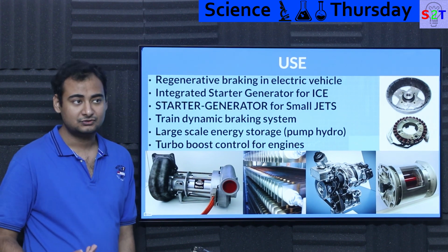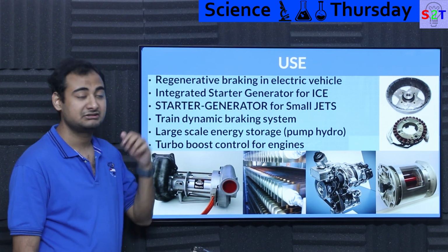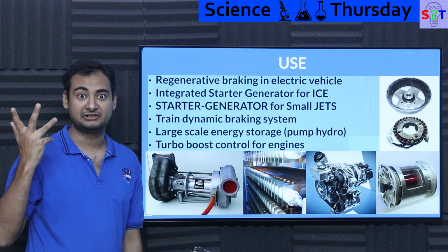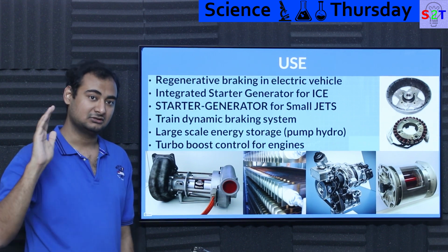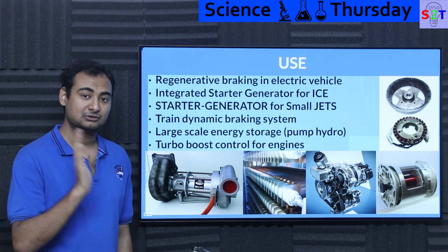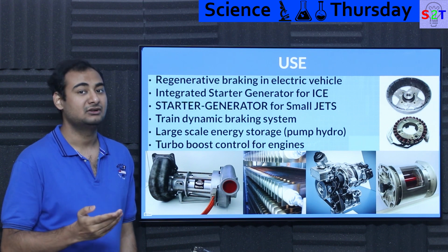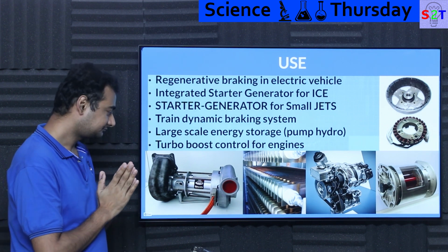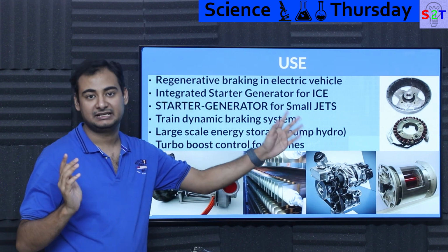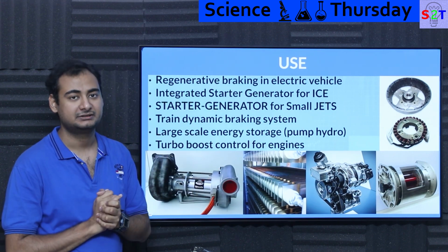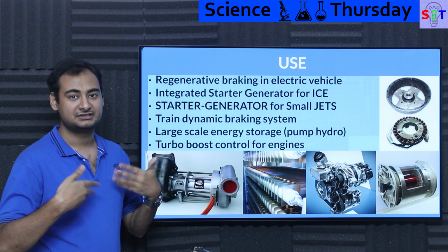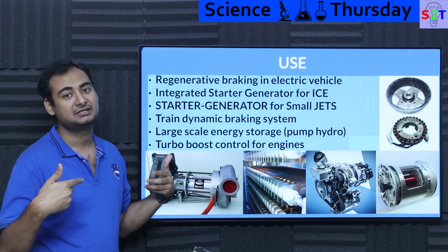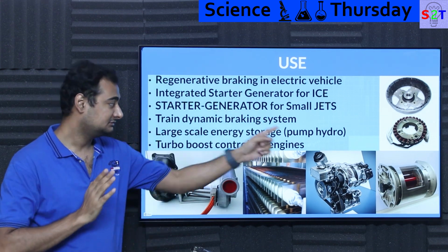Well, reality is, most of you have heard of it, specifically regenerative braking. Every time people are like, regenerative, what is that? It's like when you are going at, let's say, 100 kmph and you want to apply brakes. In an electric car, the brakes will not engage if you press it lightly. All it will do is trigger a system. Basically the induction motor is told, hey, will you start acting like a generator? And then it will sap the energy. Basically it will take the rotational energy that is in the wheels and directly turn this puppy.